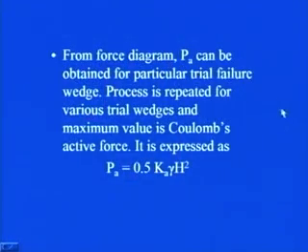Let us put it in words in the subsequent slides. You see that from the force diagram, this PA can be obtained for any particular trial wedge. As I told you, we really do not know along which wedge the failure will take place. So, we have to try for many wedges. Any particular trial wedge we pick, we find out the value of PA.